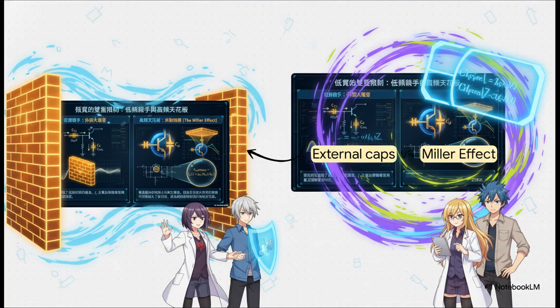So what's actually causing those cliffs? Well, on the low frequency end, the culprits are the external capacitors. The coupling and bypass caps basically act like a brick wall to slow-moving signals because their impedance shoots through the roof. But the high-frequency ceiling, that one's a lot more insidious.